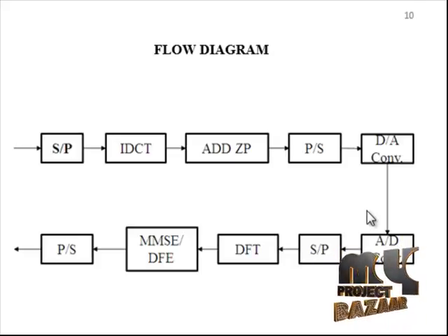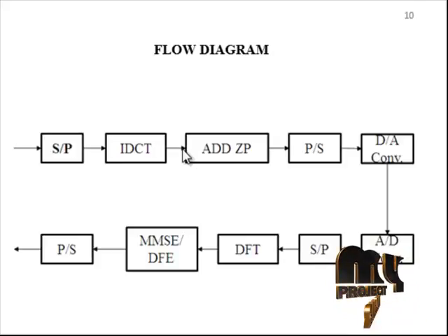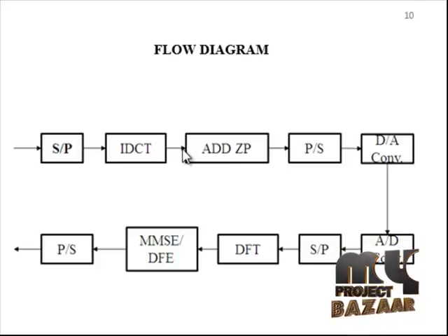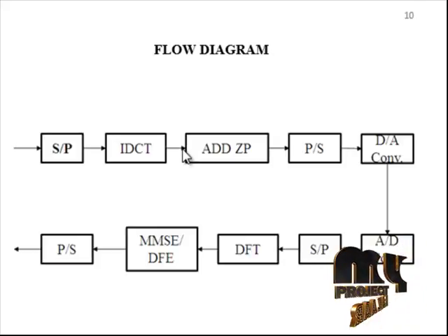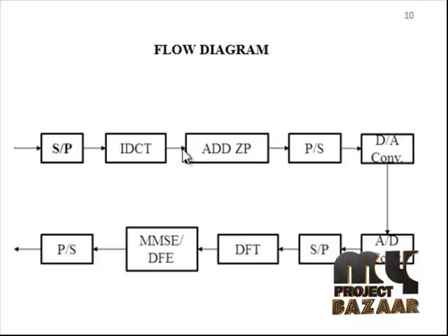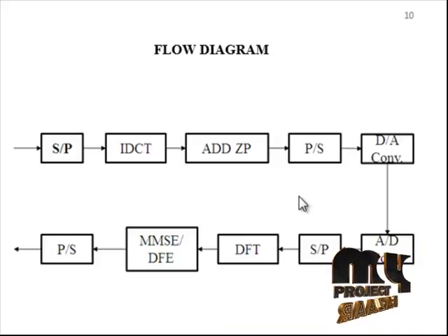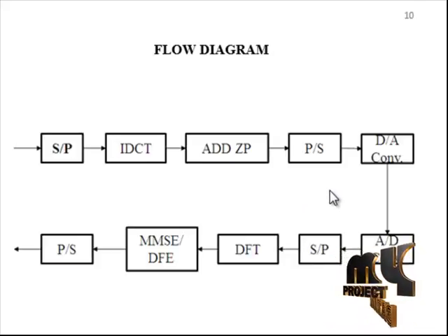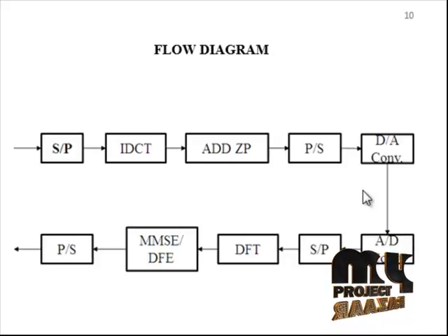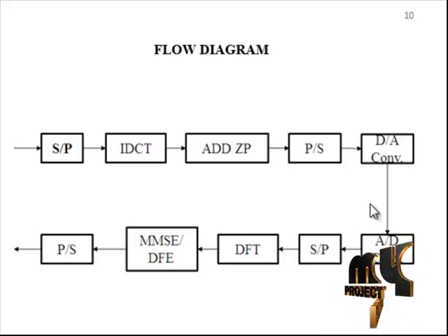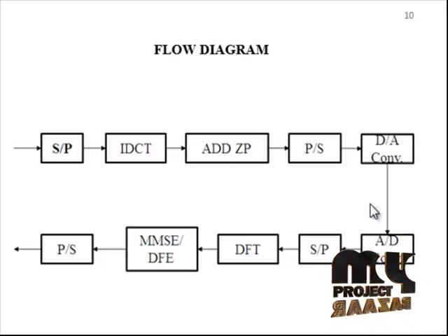The discrete cosine transform has been implemented for double side band signals, while for single side band signals the real-to-complex symmetric property of the fast Fourier transform or the inverse fast Fourier transform is proposed. Due to the limited bandwidth associated with multimode fibers, OFDM can be considered an effective solution to combat optical modal dispersion in MMF-based transmission links.